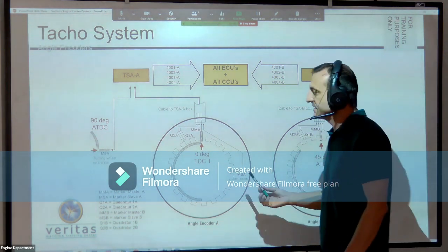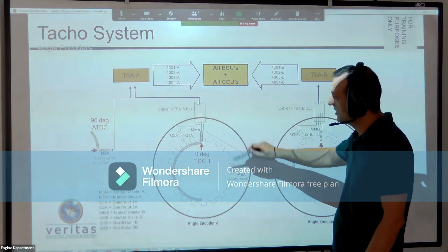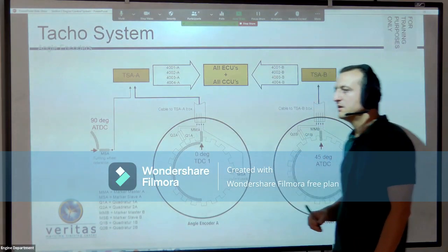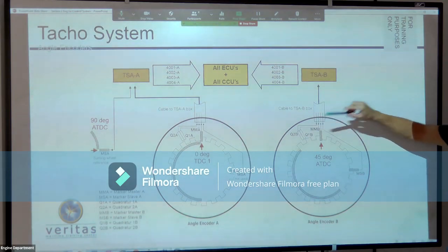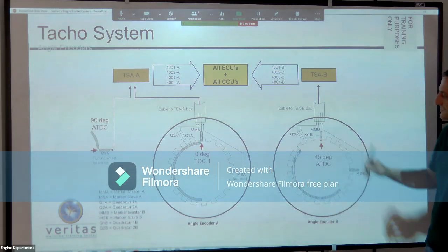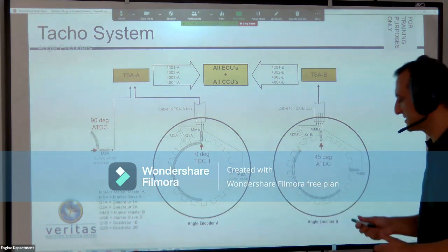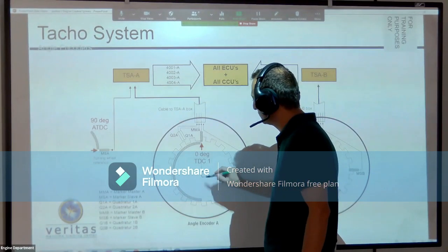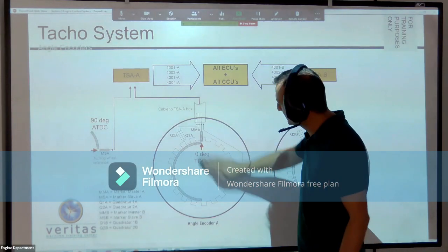On the outer part, the static part, you will find on each encoder 4 sensors: 2 marker sensors, named marker master A and marker slave A, and 2 quadrature sensors for encoder A. For encoder B, the sensors are named marker master B, marker slave B, and quadrature sensors. Similarly, you'll find a semicircular ring and a 360 teeth ring. Gentlemen, between the marker sensors we have a deviation angle of 90 degrees. So we have 90 degrees between the marker and slave sensors.